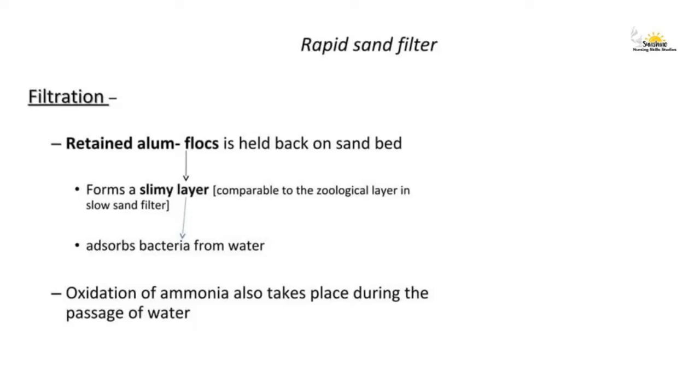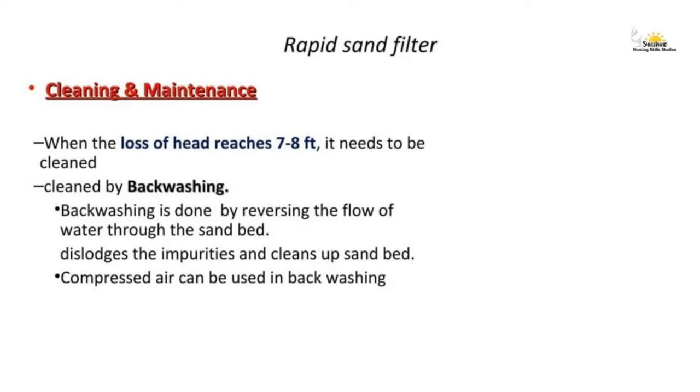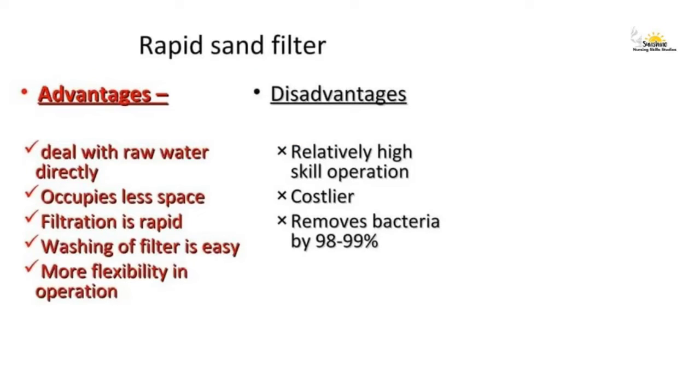And lastly, the filtration, where whatever dirty parts are left after sedimentation will get settled on the filter, and then the cleaning takes place. When it reaches the maximum, that is 7 to 8 feet, it needs to be cleaned. It is cleaned completely by backwashing.